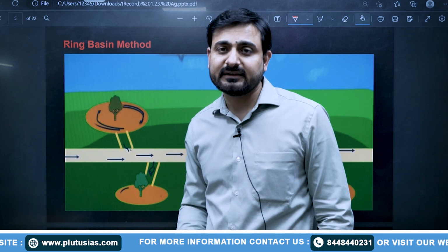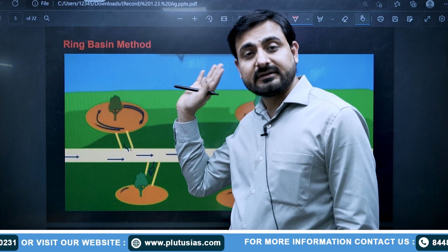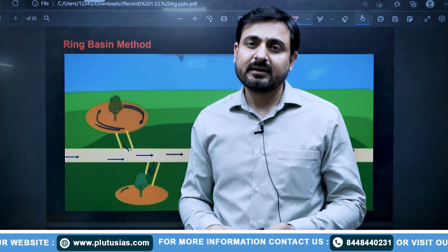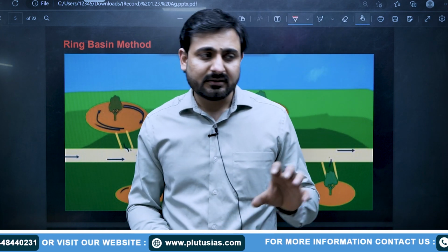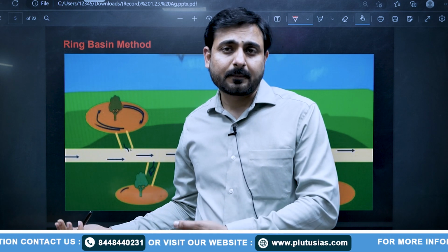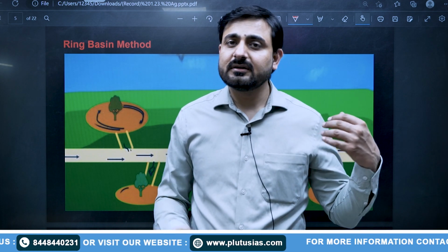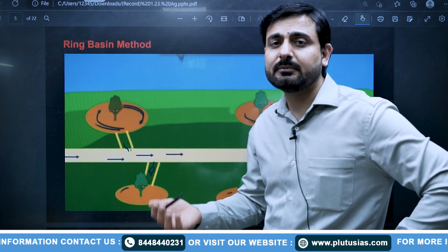Now moving towards the ring basin method. It is again a modified version of the previous one, the check basins method. Here, water use efficiency further increases. This is not suitable for all crops, especially grasses, the grass family crops. For wheat, paddy, maybe maize, or other crops like cotton and millets, this circular ring basin method is not very well suited. It is more suitable for orchards.